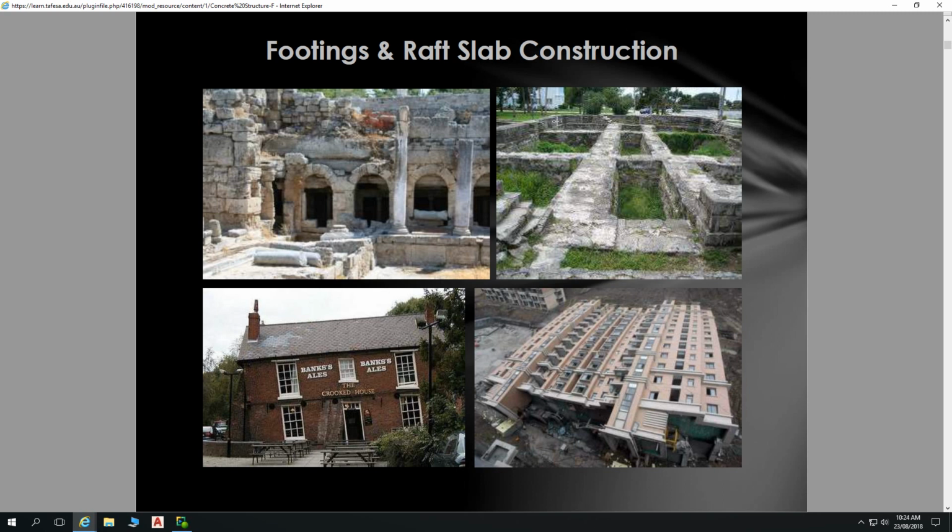But any shape that's happening on your formwork translates into the concrete, and you can see that really well on that wall over there. You can see it from a distance in some regards, but then when you get up close, you'll see where they've used second-hand bits of form ply that used to have nails in it, some little pieces of the form ply that have come out, all that sort of stuff. Any defects on that face will show up in the concrete. So I'll pass that around, and you'll see some defects on that form ply, and that is going to provide a mark on that concrete once that concrete has gone off.